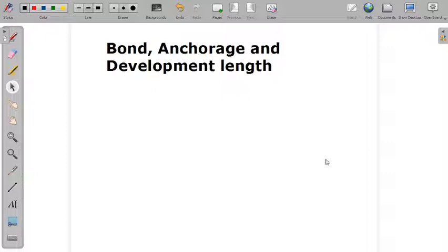We will see this. Okay, the local bond stress varies along a member with the variation of bending moment. So this bond stress in a particular area is also varying depending on the bending moment. Okay, the average value throughout its anchorage length is designated as the average bond stress. Okay, so how it is done, let us see one by one.